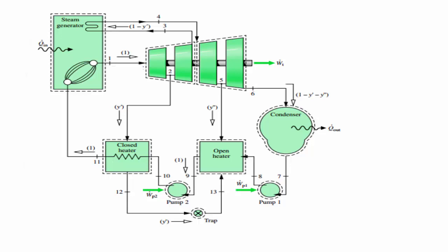So the steam goes from the first turbine, and as it goes to the second turbine, it is extracted and goes into the closed feed water system. Now the steam goes to the second turbine, and at the outlet of the second turbine it goes into the reheater, which is at stage 3, and it comes back at stage 4 and goes into the third turbine.